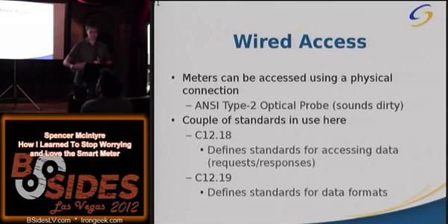I'm going to demonstrate. So first off, how do we actually interact with the meter? We have to get an ANSI Type 2 optical probe, which sounds really dirty, I know, but it's better than the Bus Pirate, that allows you to dump the information off the devices. I don't know if anybody's heard of the Bus Pirate, but that's probably some of the funnier things I've heard. Anyways,